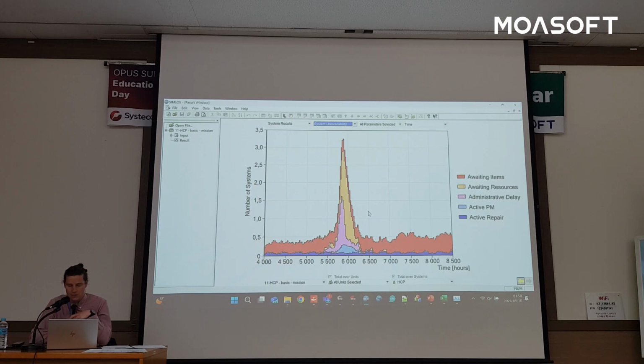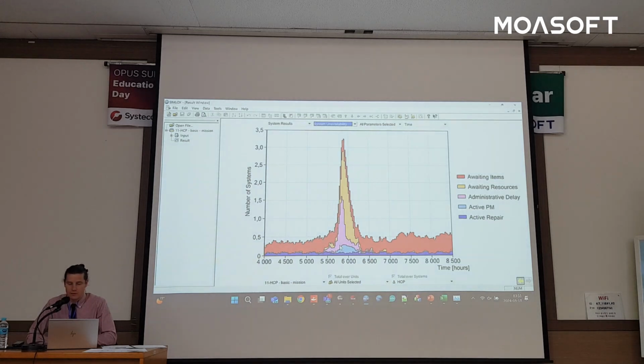So that means that they won't coincide like this, and that's something that can be taken into account because we can give something called age parameters on the systems and items. So you can specify where we are in the maintenance cycles in terms of preventive maintenance, of course. Random failures are independent of the state because of the Poisson process assumptions. But for scheduled maintenance, PM, you can define where in the cycle you are at the moment, which will give you a more precise answer